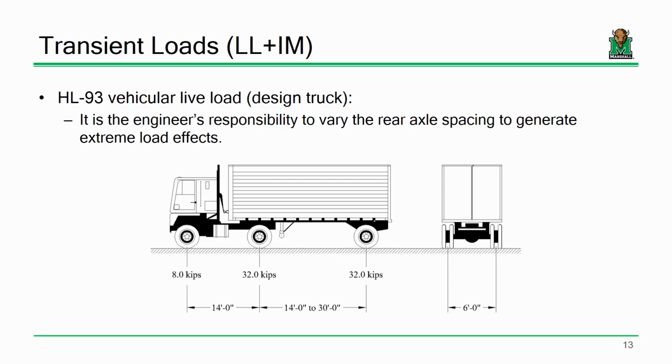But when you're getting into that level, like if you were actually doing a full-blown 3D computer model, AASHTO will tell you how to apply that load. It will say that this, let's say this front wheel of 4 kips, must be applied over a 10-inch by 20-inch area. That's the contact area. So you would calculate your pressure and then put that on your finite element model, or if you're doing this 3-dimensionally. Okay. So far, so good?